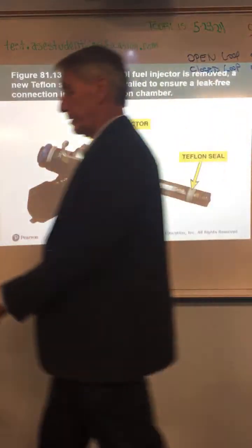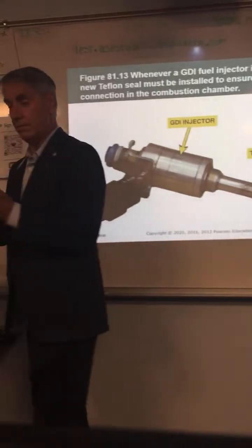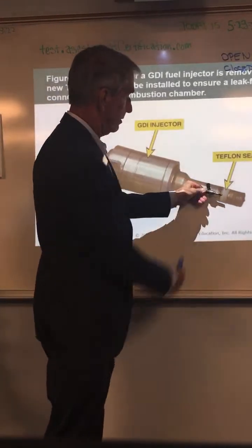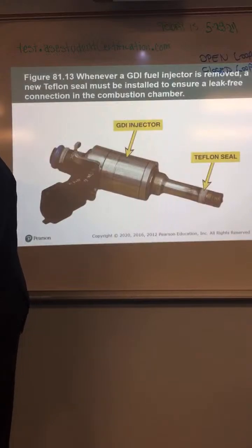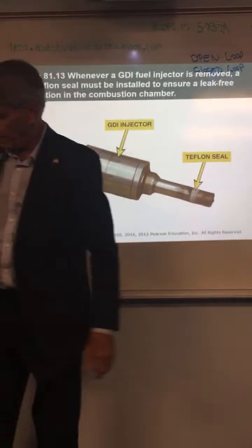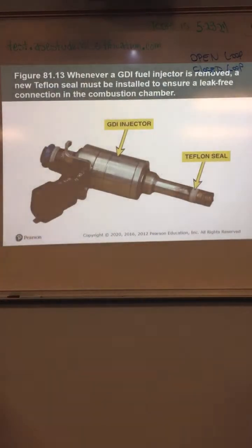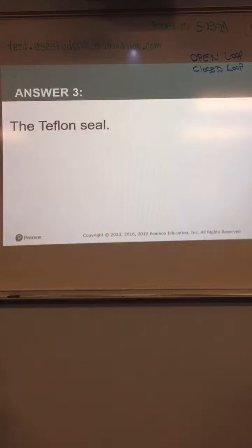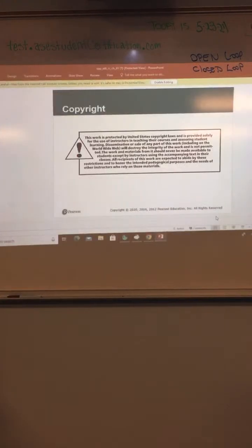This injector, just like you see here, they're talking about that seal right here on the injector. This little seal right there, it's supposed to be replaced when you pull the injector out or replace the injector. Actually, if you replace the injector, it's gonna have a new one, so don't worry about that. All right. What should be replaced? The Teflon seal. There you go.